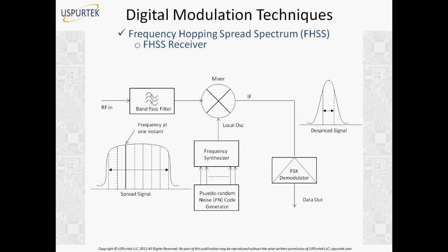Defense work, yes, in defense work too, because you need 100% secure and reliable communications. Whether it's fading or not fading, whether it's raining or not, you must be able to transmit data. That can be achieved by frequency hopping. You make the band very wide and hop the frequency so that at some frequency you are able to transmit. So that is why commercially it's finding use in machine-to-machine communications. In fact, there is a protocol which is already validated by the Federal Communication Commission. It's called Weightless. The Weightless protocol has selected the FHSS technique and frequency shift keying and MFSK for machine-to-machine communications.